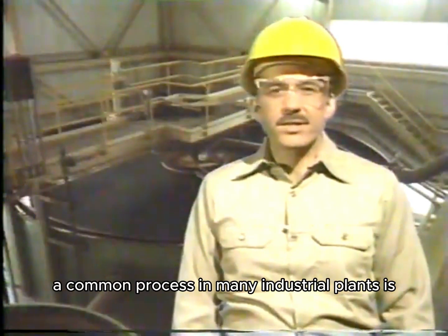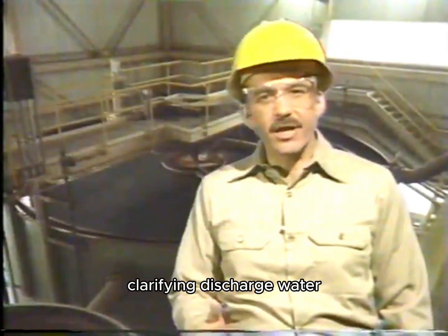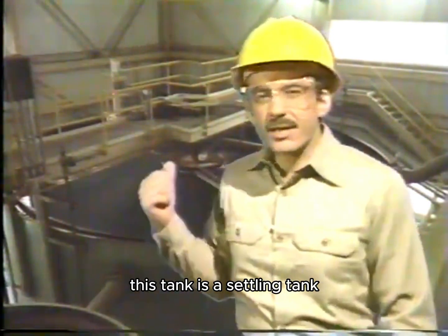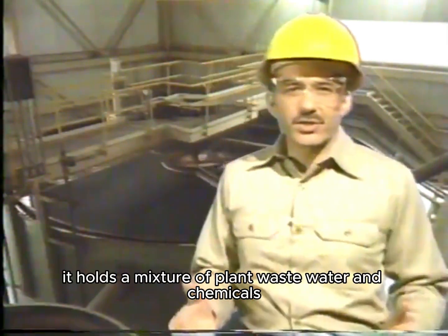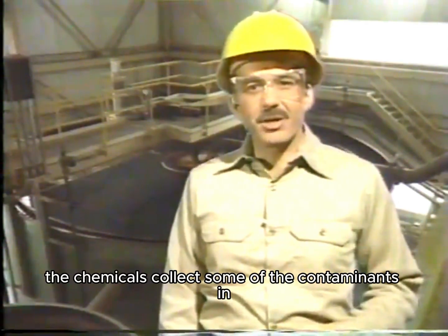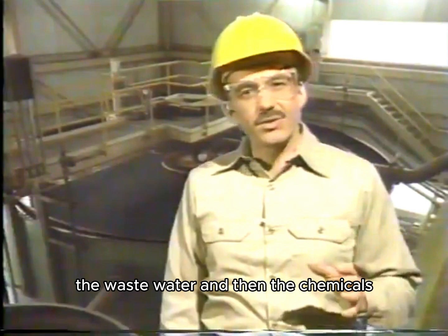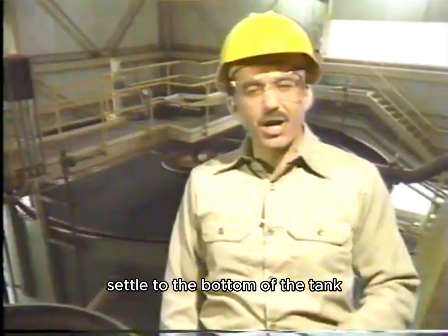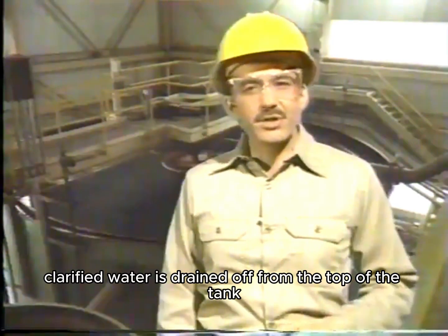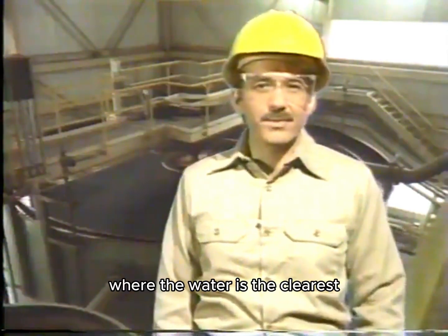A common process in many industrial plants is clarifying discharge water before it's returned to a river or a lake. Now, this tank is a settling tank. It holds a mixture of plant wastewater and chemicals. The chemicals collect some of the contaminants in the wastewater, and then the chemicals, along with the contaminants, settle to the bottom of the tank, reducing the concentration of suspended particles. Clarified water is drained off from the top of the tank, where the water is the clearest.